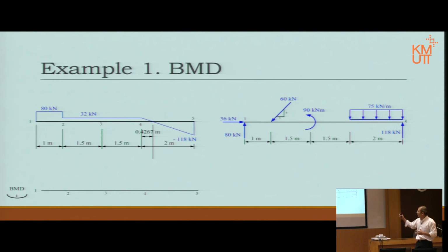That is again the beam. Start off at 0. Before point 1, everything is 0. Then at point 1, there's no moment applied, there's only forces. But forces do not change moment, therefore it stays still. At point 1, it is just 0, staying at the same place.